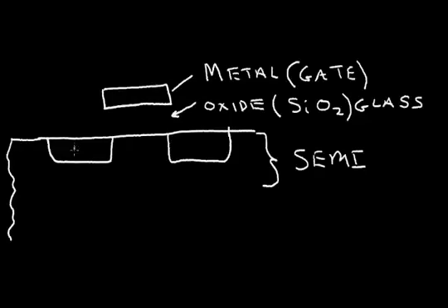And let's presume that this is an N-type dopant. And our starting wafer is P-type silicon. So this silicon region is the semiconductor. And thus, the MOS refers to the metal gate, the oxide under the metal, and the silicon semiconductor material under that. So what does the FET part stand for?